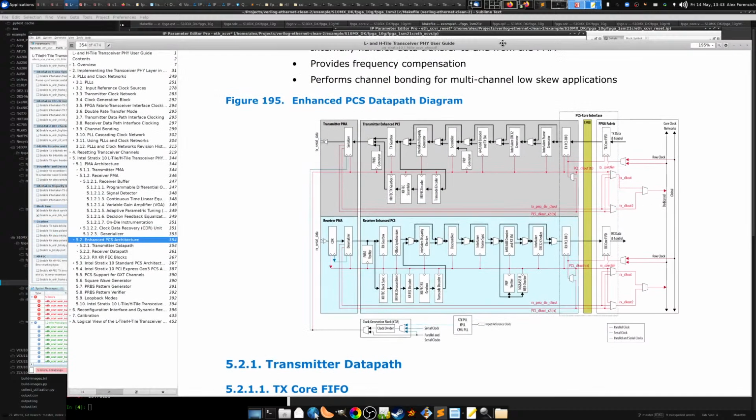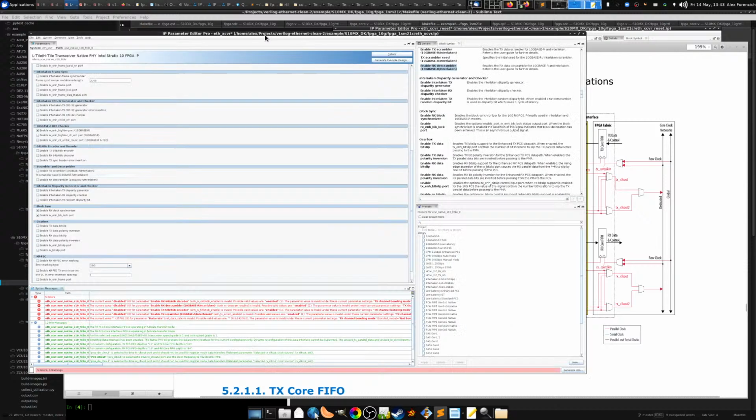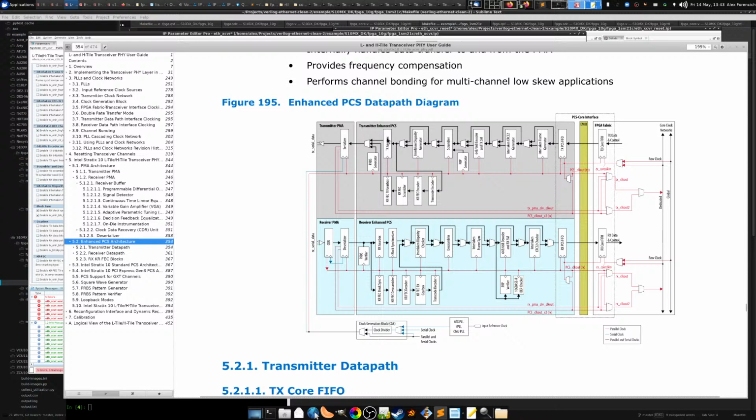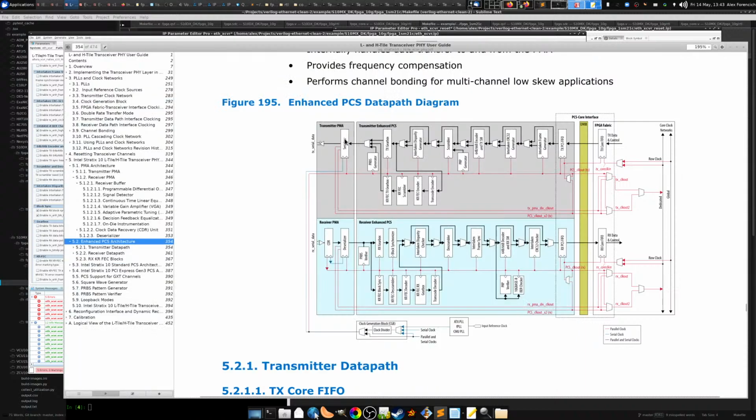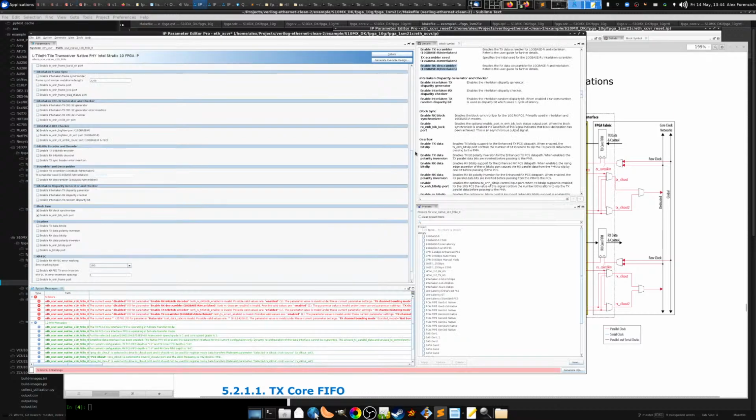All right, well, whatever. The main thing that I need in the transceiver for what I'm doing is the gearbox. There's a TX gearbox and there's an RX gearbox. The reason you need the gearbox is because the serializer is always basically a power of 2 width, possibly with some factors of 5 because of all the 8b/10b stuff. So this can be like 16, 32, 64 bits. But for 10G Ethernet, we're moving 66-bit frames. So the gearbox is responsible for making that conversion.